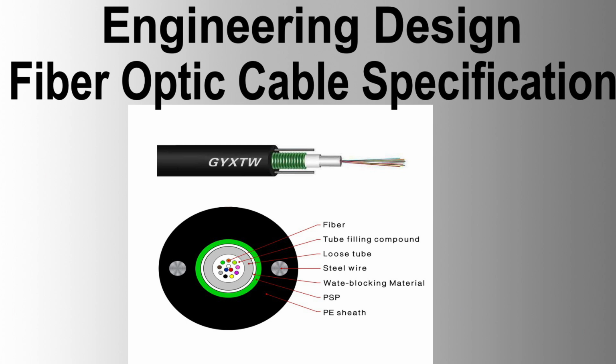Splicing environment. Conduct splicing in an air-conditioned, dust-free controlled environment. Use core alignment fusion splicers and semi-automatic cleavers for precise cuts. Protect fiber optic splices with mechanical sleeves, inserting them into the splice closure's cassette, then carefully closing the closure. After splicing and testing, clean and close the chamber. These procedures ensure the proper installation and protection of fiber optic cables, maintaining high standards for future reliability and performance.